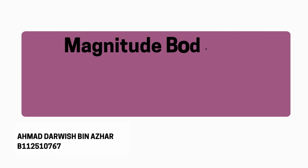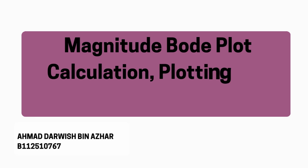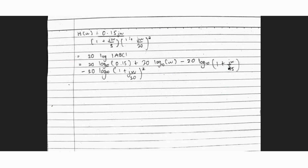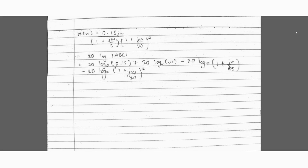Assalamualaikum warahmatullahi wabarakatuh. My name is Ahmad Darwish and I will be explaining how to solve the magnitude Bode plot for question A. First of all, we need to use the standard equation that we have found, and then we use the general equation, which is 20 log base 10 ABC, and substitute all of this into it, which will be 20 log 0.15 plus 20 log ω minus 20 log 1 plus jω over 5 and minus 20 log 1 plus jω over 20 squared.